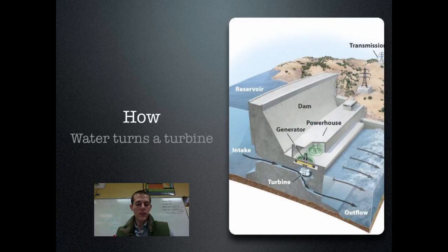As I mentioned just a second ago, the way that we create electricity using hydroelectric power is by storing water, which runs a turbine, which creates electricity. Here's just a general water impoundment system. So you've got your dam. The dam blocks the river, which creates a reservoir. This is your water storage. Within the dam, there is a water intake. The water goes in, it flows through the turbine, which is right here, which turns the generator and gives us the power and the electricity that goes out to our power lines, and then the water just flows on past the dam. So it's a really simple system.